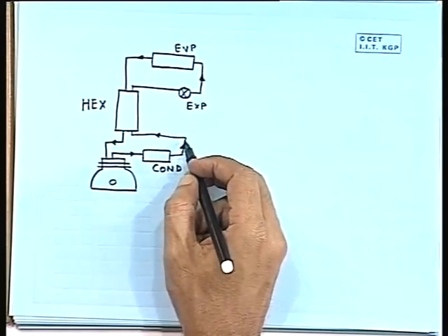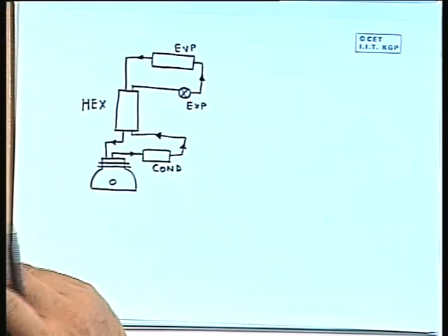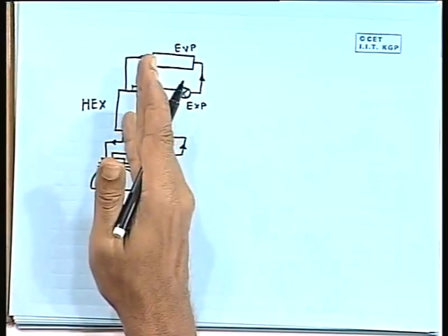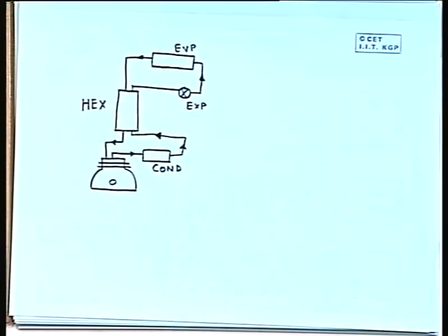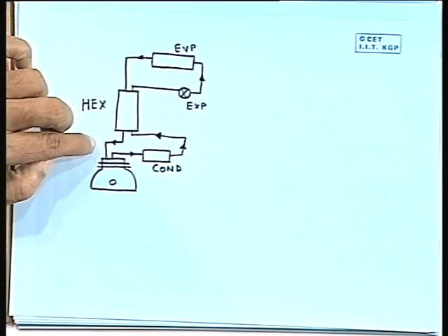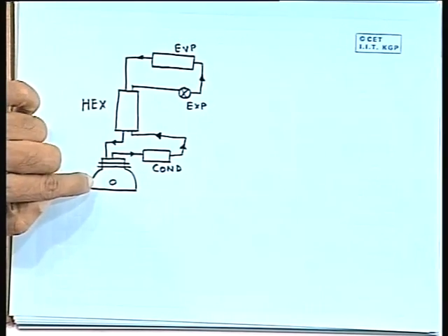What we are getting is that after the condenser, when the refrigerant is coming out, it still has a slightly higher temperature. So, this heat can be utilized by the refrigerant which comes out of the evaporator, so that it guarantees that the refrigerant will enter the compressor in the superheated condition. All right. So, this is not there in small systems, but in large refrigeration systems we will have this type of arrangement. Well,